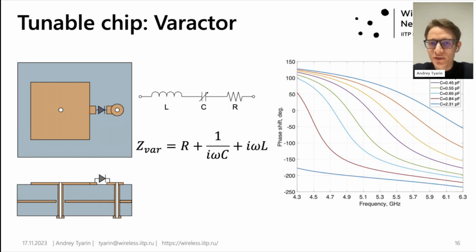The parameters of the UC were selected so that 5.3 GHz is the central frequency of the band, where the difference of phase shifts between the curves remains almost constant. Thus, by changing the voltage on the varactor, we adjust the phase shift in the range from 0 to 300 degrees.